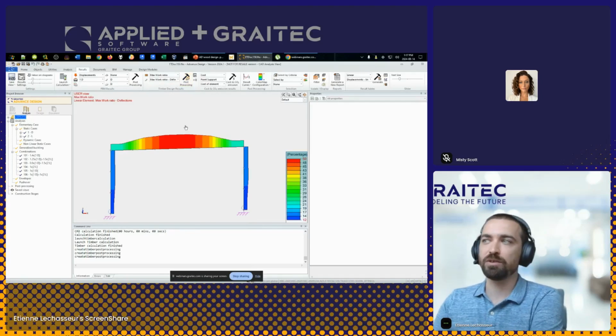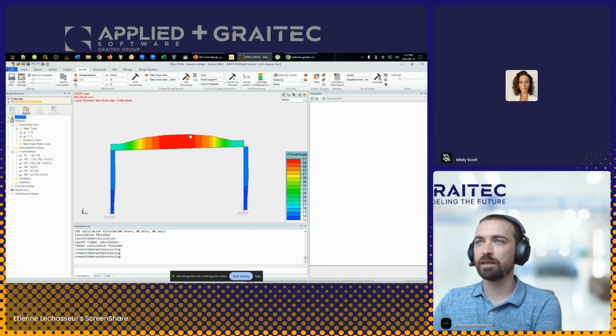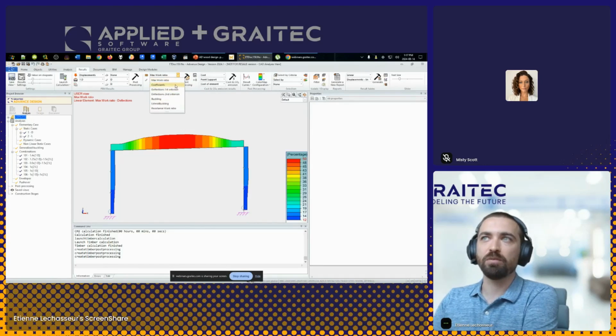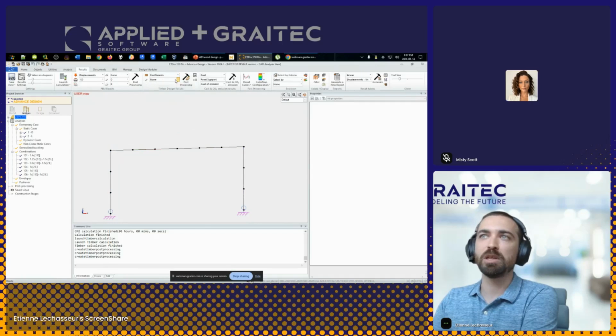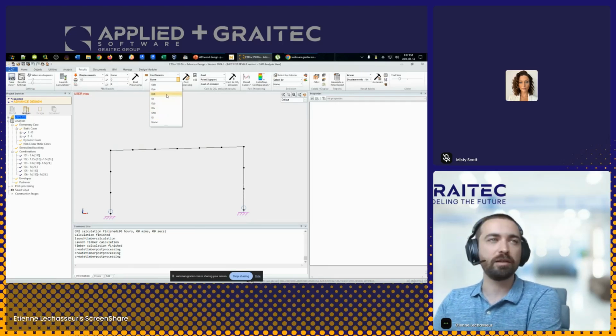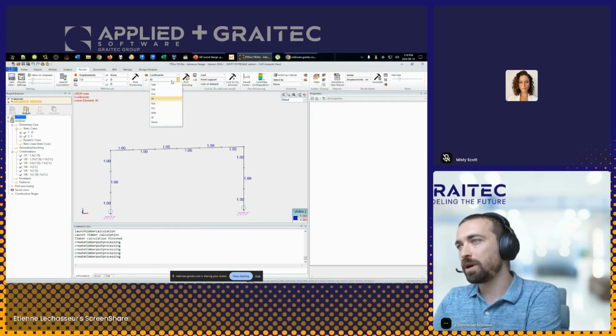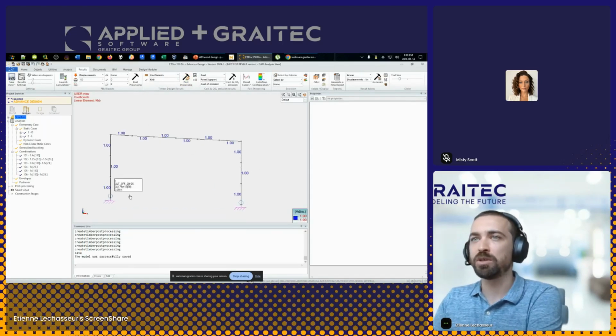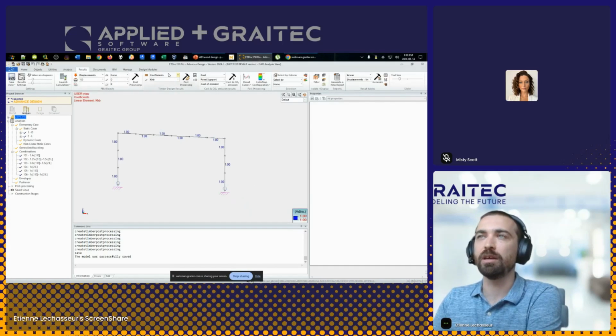and 50% deflection. There were some default values, so that's why we get the results even if I didn't define them. There's a lot more things we could display graphically. For example, we have not all, but many of the K coefficients. For those who are from the US, this is the equivalent of the C coefficients. There's one for temperature, for whether it's treated or not, and so on. Here, since I kept the default values, it's probably all going to be 1.0, just to show that you can display them graphically.